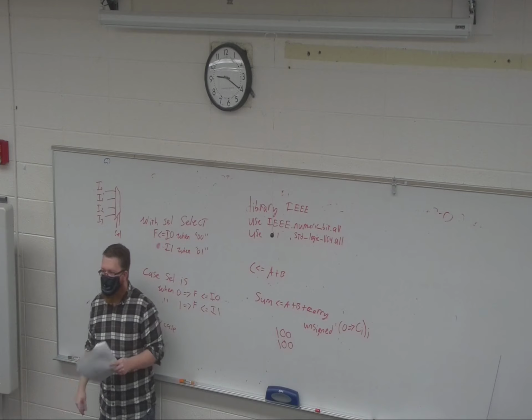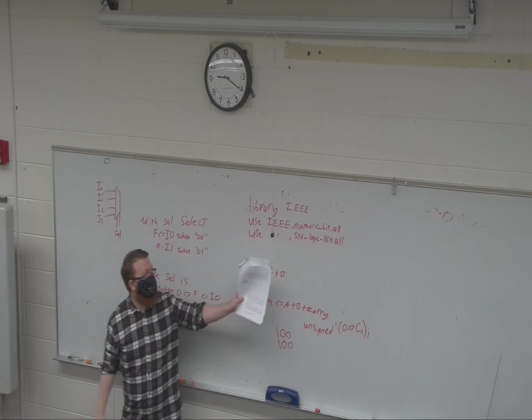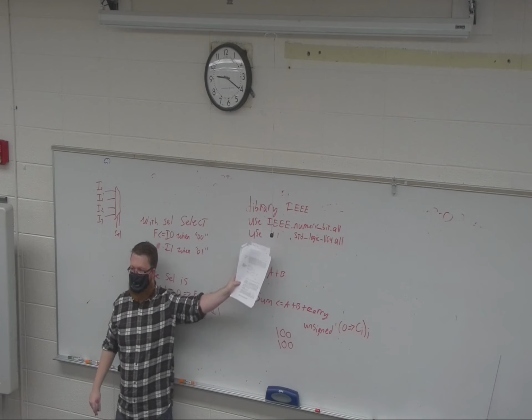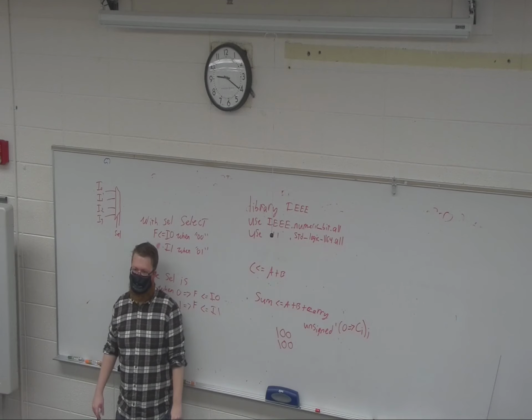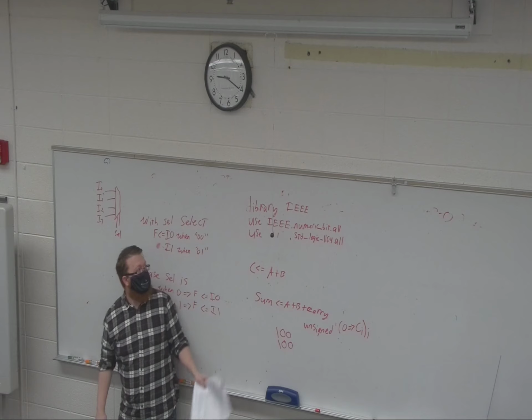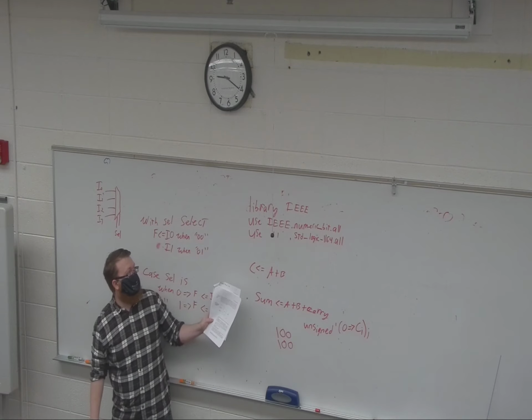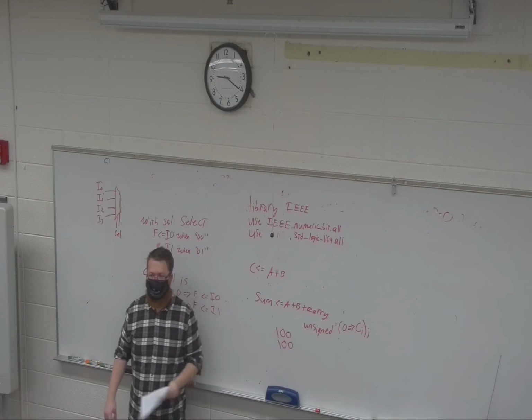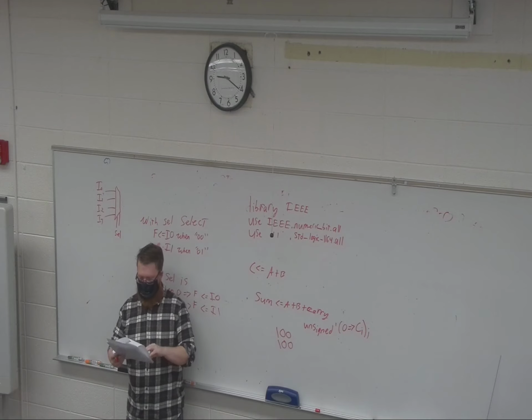Now, if you ever look at a VHDL example, almost all of them will use this library because this allows you to start using addition on bit vectors. I always use that library, and I start using the standard logic types, because then I can add them together, which is really quite helpful.